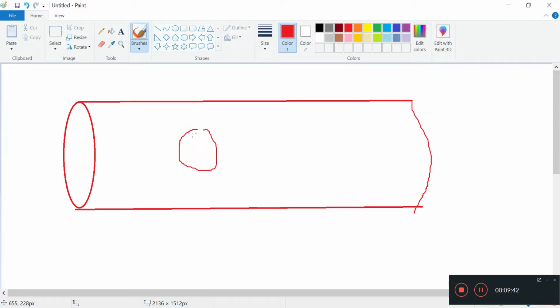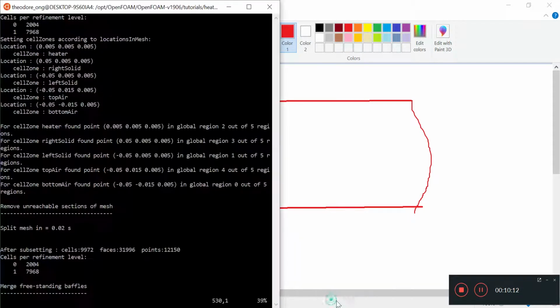I want to have a pipe flow, and then a sphere in there, or maybe a collection of spheres, or some packed bed kind of thing. And I want the fluid to flow through, and then see the effect of heat transfer on these spheres. So doing a snappyHexMesh and an STL for that one may prove to have some learning curve to it, but that's for next time.